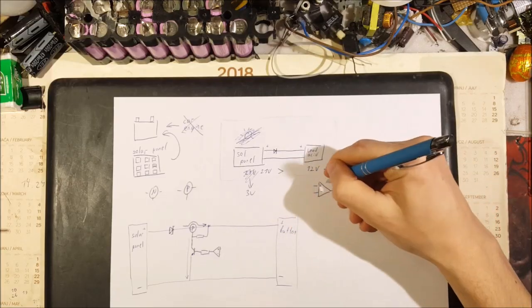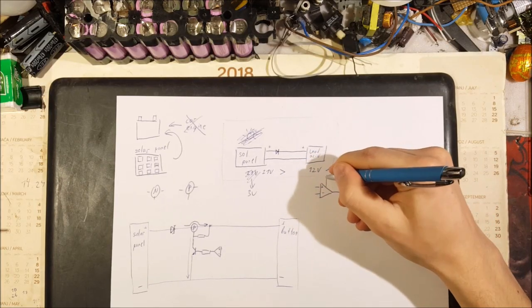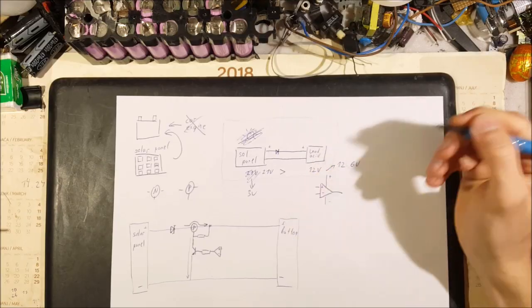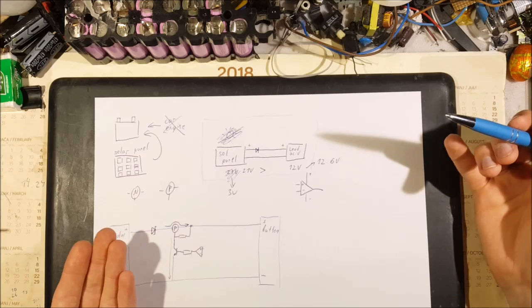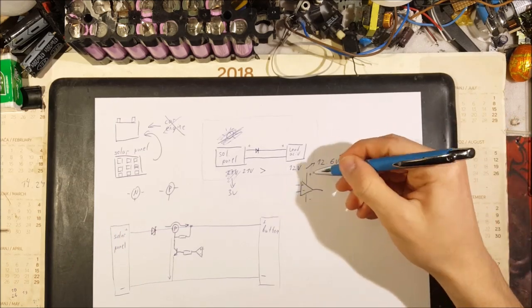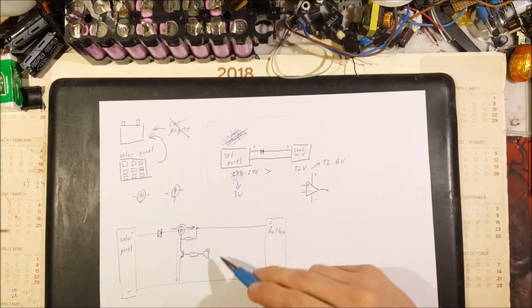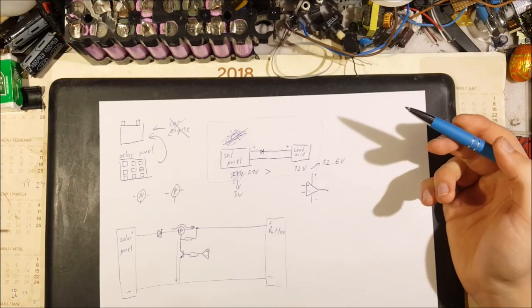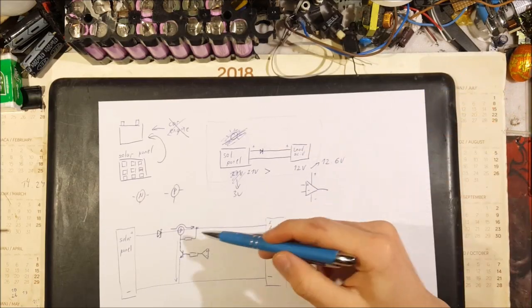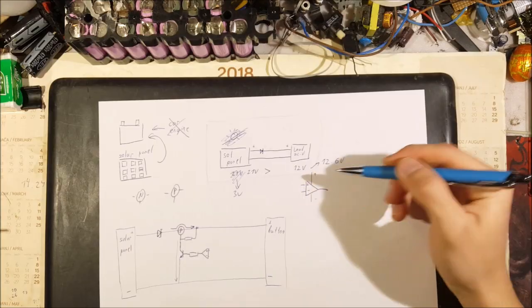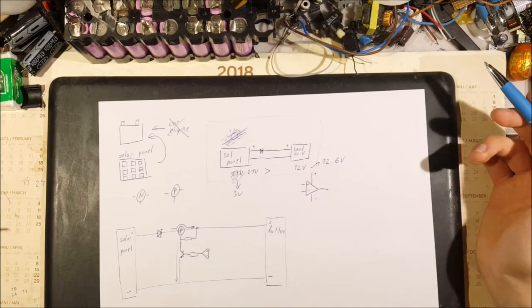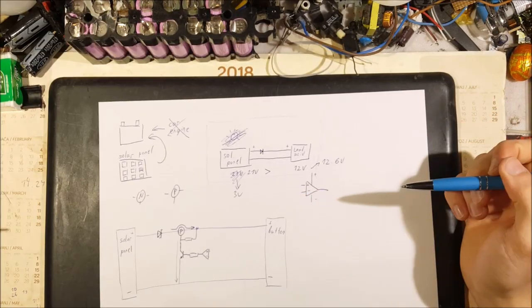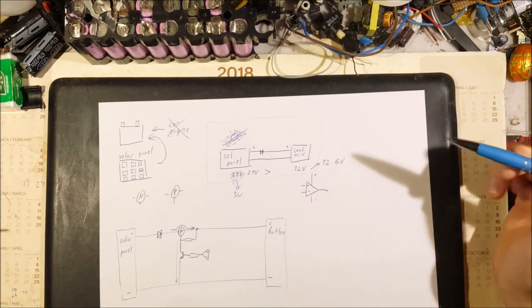If you want to be more precise, you will draw the positive and negative supply, meaning that it is an integrated circuit, so it needs power. So in our case, our positive and negative are connected, of course, straight to the battery, so the chip gets power from the battery, and then we have two inputs and an output.